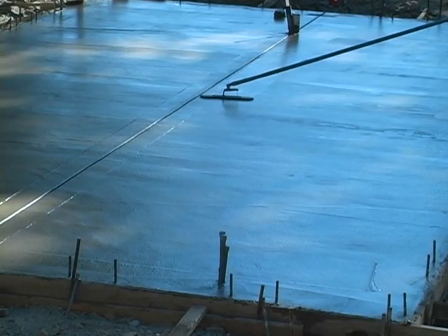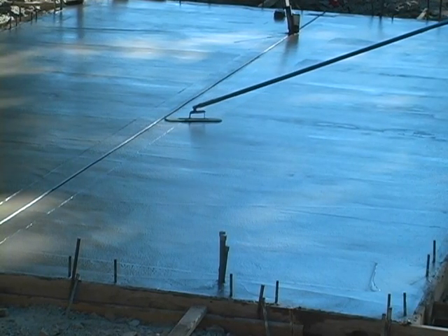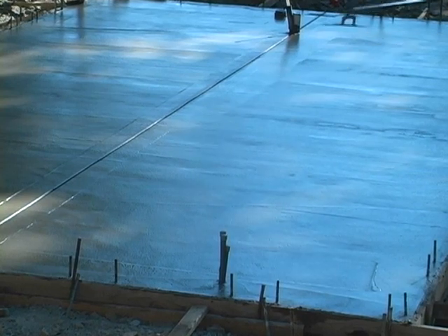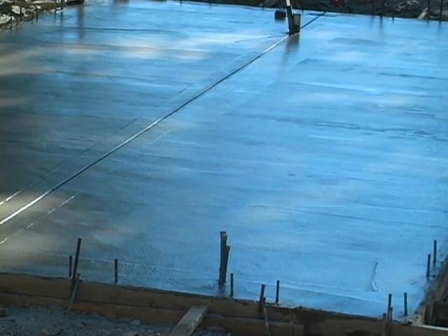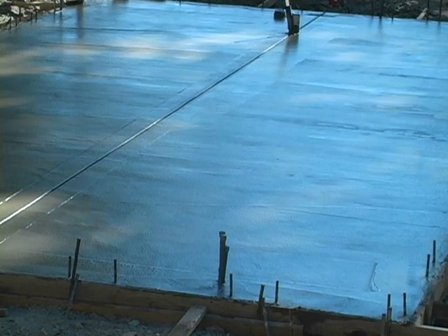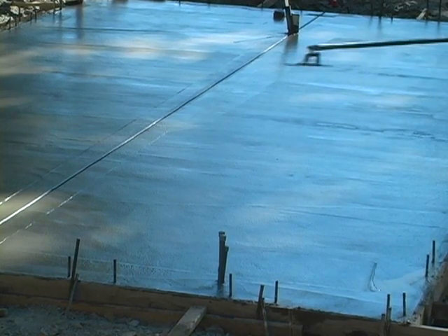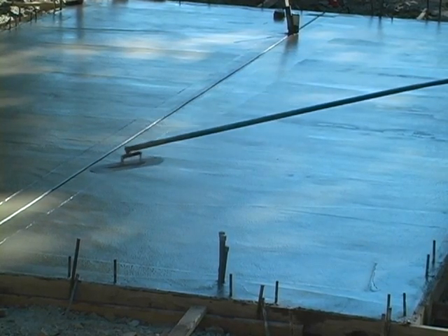And regardless of how good a job you do pulling or pushing the groover, you're going to end up with lines outside of the groove that you wanted. Those represent the outside of the plate that you were just pushing to make your groove. So you need to come back with a trowel and clean those up.